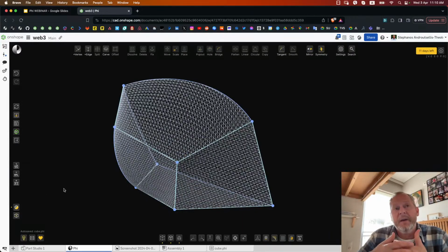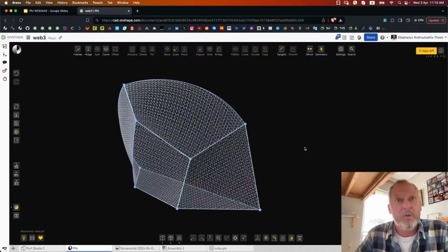So we triangulate the faces at specified densities of triangles simply for visualization, in order to be able to show this on the screen. The underlying quality of the faces is not related to the number of triangles. It's actually very high precision, and we can see this if we export faces and study them in, for example, Onshape's surface examination tools.